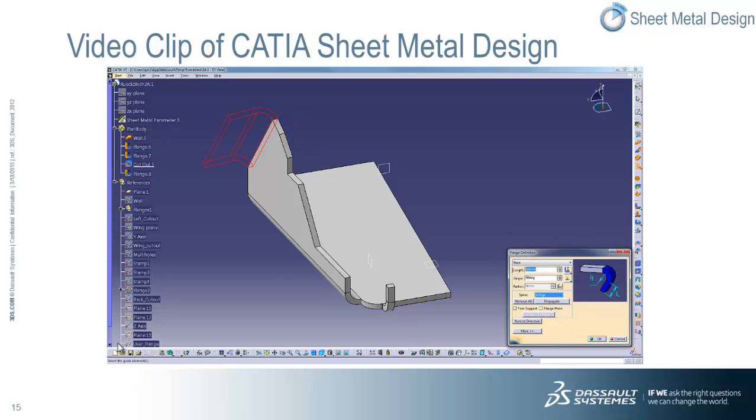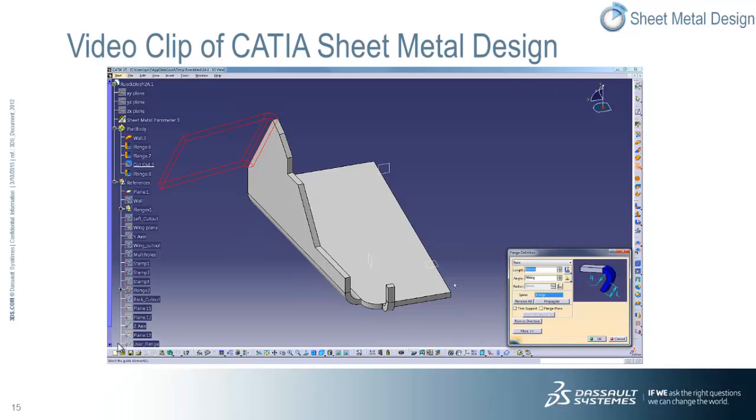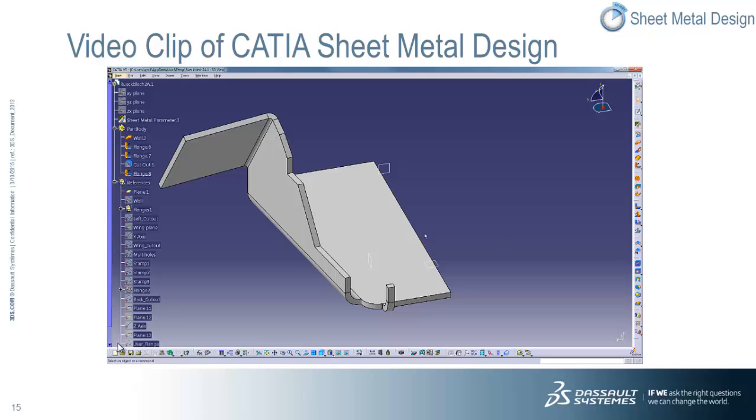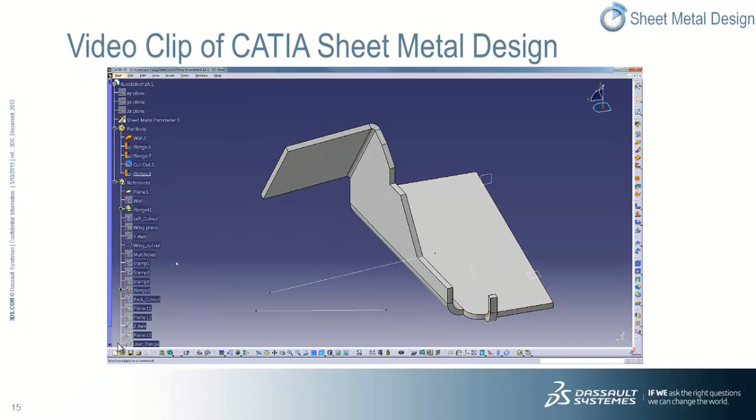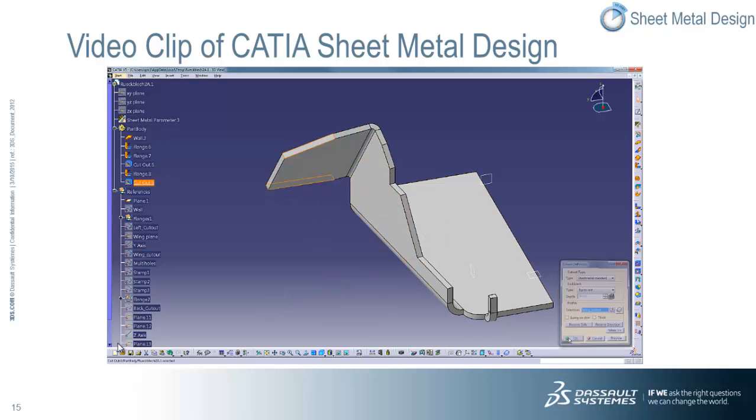Then we create another flange. We then do another cutout based upon a specified profile and apply some rounded corners on the new flange. Then we create a flanged hole on the new flange by specifying the appropriate parameters within the pop-up window.